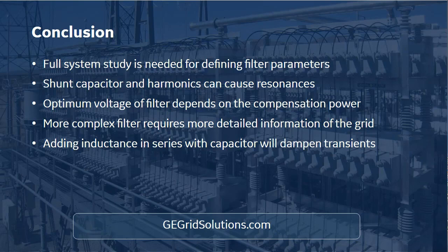We will have an impedance sector from the TSO, and then we will have the information from your network, and when you combine them, you make enough simulations with different network impedances, and then you will get the worst case, which you will use for finding the parameters for your components. Hope this clarifies it.